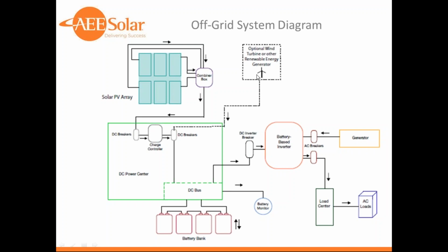And then if you have any other kind of inputs, wind or hydroelectric or solar input, they're basically just combined the same way that another PV array would be combined, also going through a DC breaker and through some sort of charge controller. Some wind turbines have built-in charge controllers, some need external charge controllers, depending on the brand. Hydroelectric units generally need external charge controllers. So it's just another source, connected to the DC bus and charging the battery.